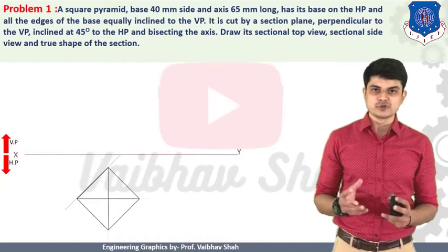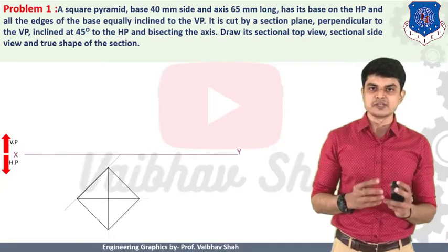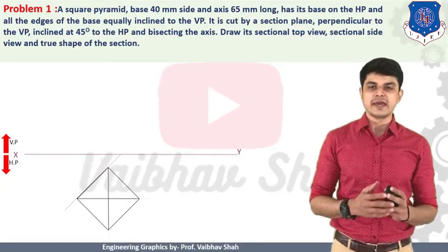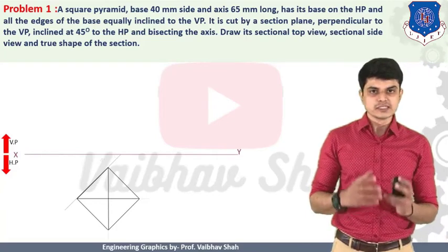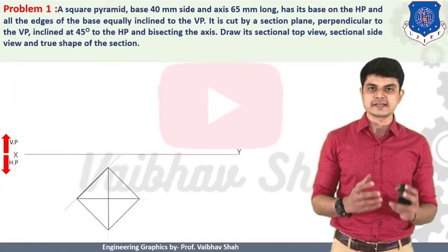So when you draw the square by its diagonal points, we will have one center point generated, which is nothing but showing the apex of the object. So our object is what? Square pyramid. So we have got the apex of your square pyramid at the intersection point.